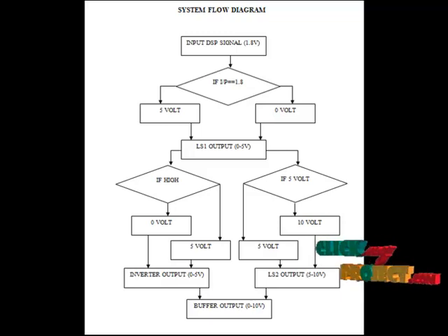The output terminal of the CMUT device is connected to the DC bias voltage through a large bias resistor and a bypass capacitor, for biasing the CMUT near the breakdown voltage for high transmit efficiency. The output driver and CMUT interface is also connected to the receiver analog front end, which consists of a high voltage isolation switch and a low noise preamplifier to amplify the incoming weak electrical signal converted from the reflected ultrasound signal so that it can be processed in the following stages for image construction.